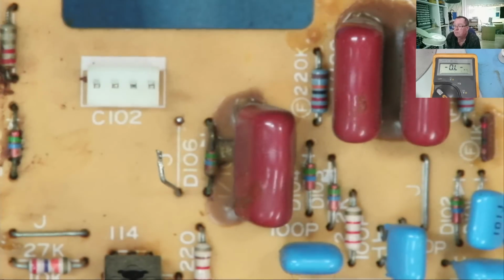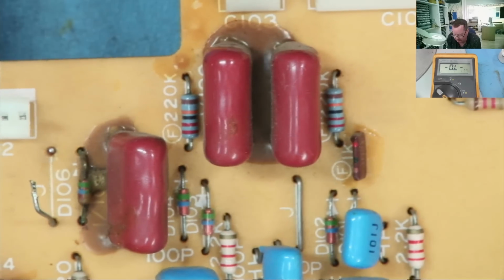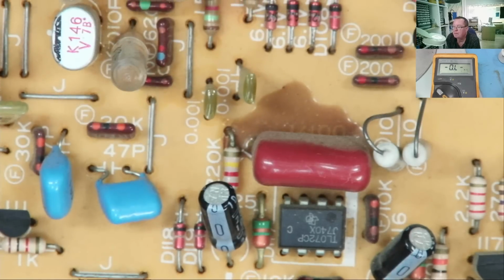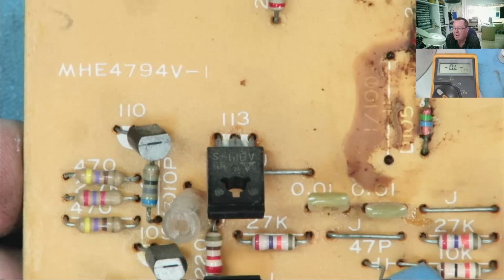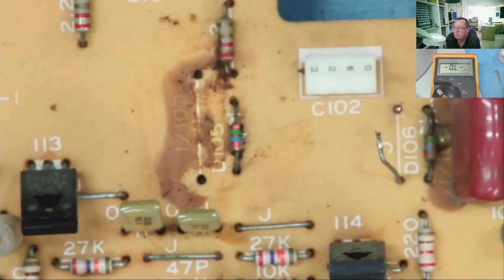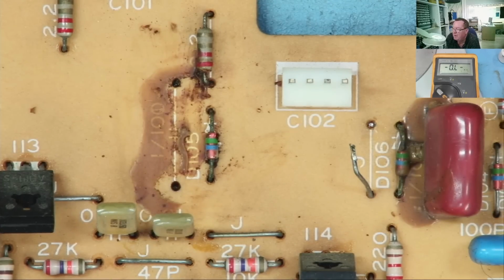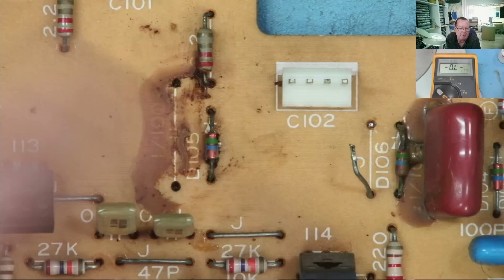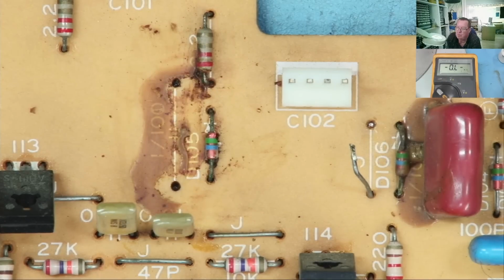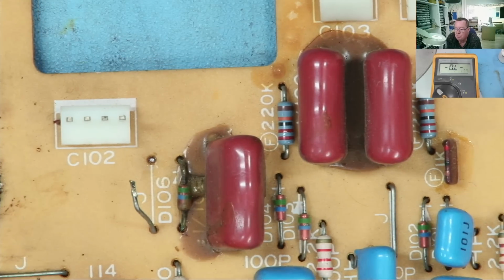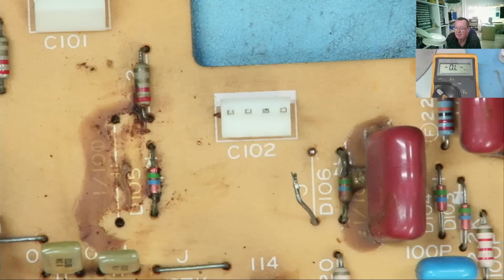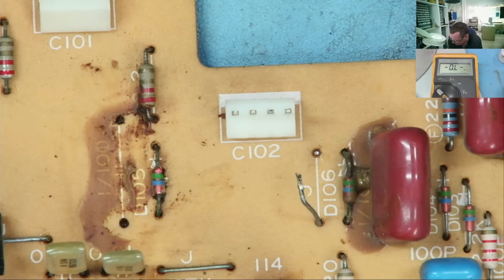Okay. There's more of it around these capacitors. Another one down there. Obviously we'll have the same on the other module as well. So there's going to be a bit more time I need to spend to actually complete this repair. But we do know that when we disconnect the cables to this one, the protect lights went off on both. So I'm happy to go away in my own time and do that now. I think I've shown you guys the most interesting thing.